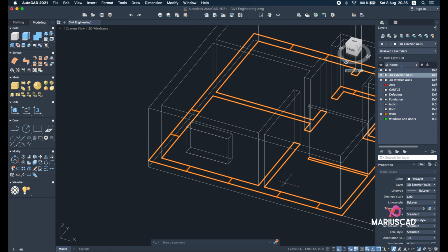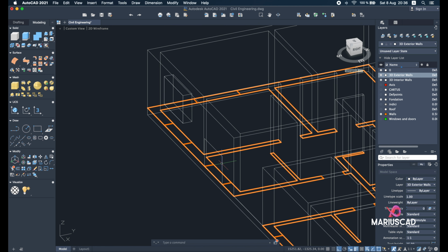Okay, so now let's do it for the other windows. So now let's go with rectangle again. Make sure it's the good plane and find the endpoint. Yeah, here I have 170, so 170, tab, 120. Move it, and press 90.